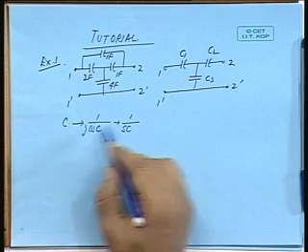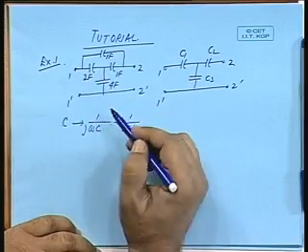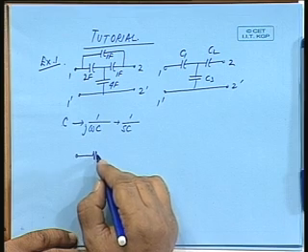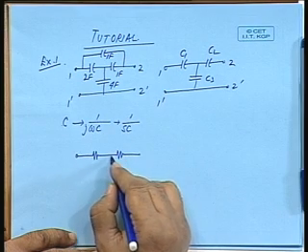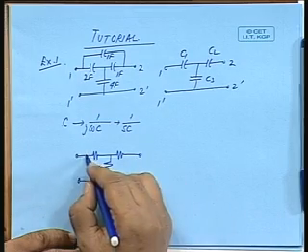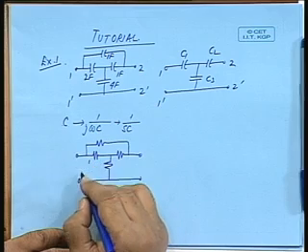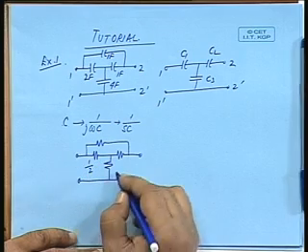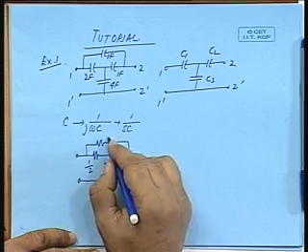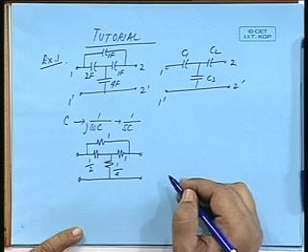That means the impedance is inversely proportional to C. So, I can take these capacitances to be equivalent impedances or even resistances, with values which will be just the inverse of these: half ohm, 1/4 ohm, 1 ohm and 1 ohm. I can replace it by an equivalent impedance circuit.